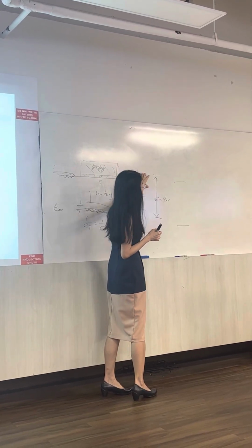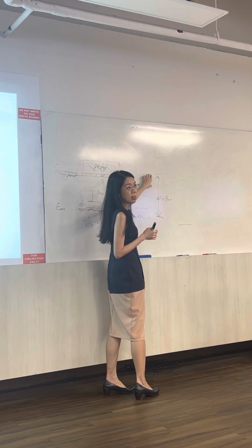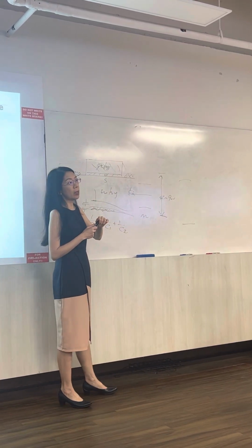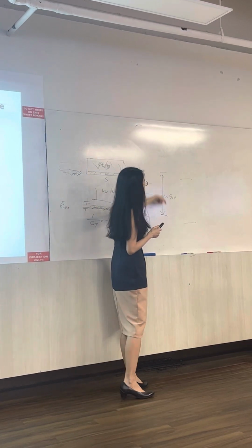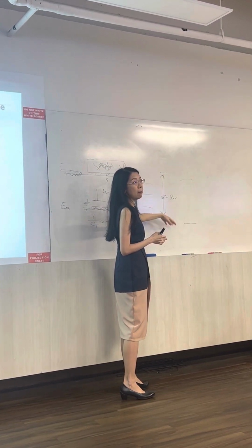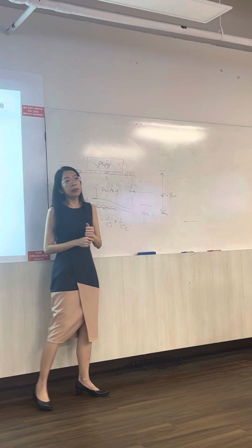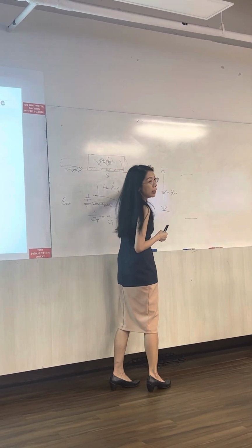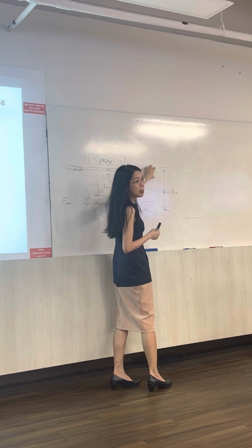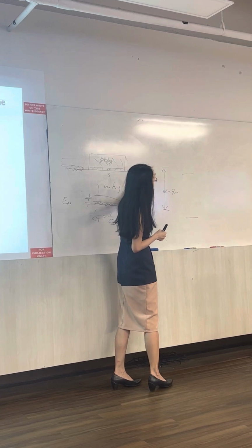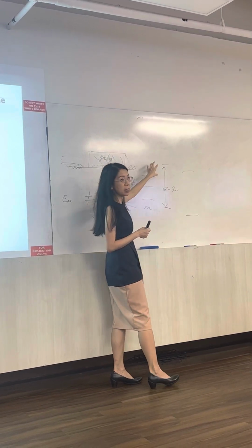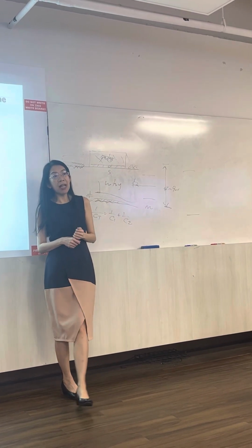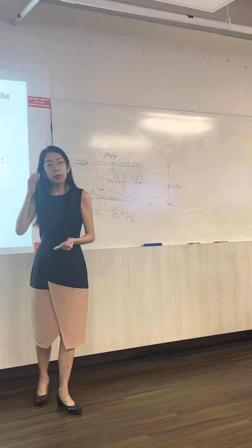There must be sufficient offset. So basically the oxide has to have a bigger gap than the semiconductor. So that this band edge offset is sufficiently wide, so that the current does not easily go through. Because you want to inhibit any leakage as well.